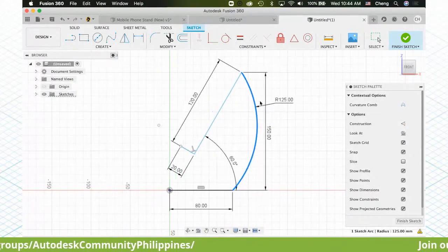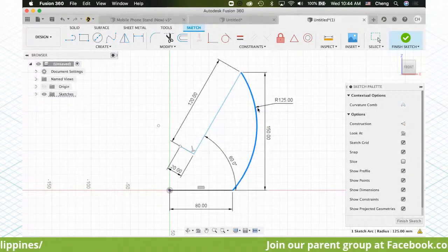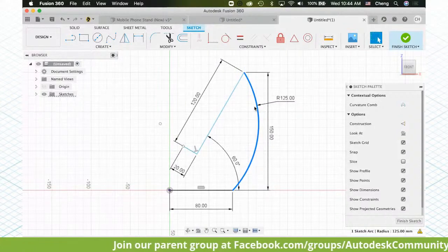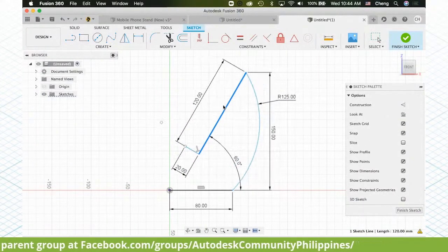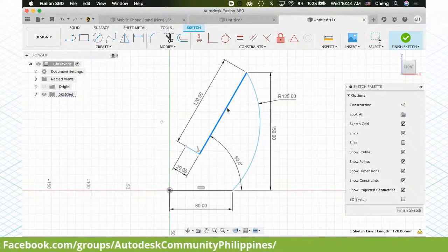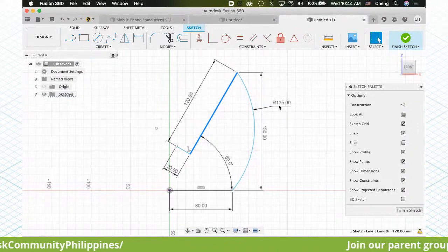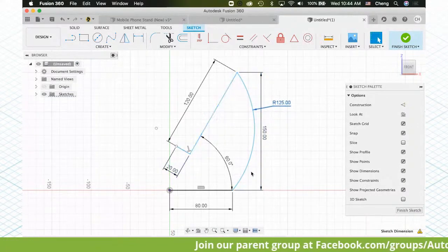So the next item, you can do a ground lock, but in this case, I don't want to lock it first because I want to look at the model outcome later on. So I temporarily just leave this model free to move. Later on, we will fix this if there's a need to. If not, I am just going to leave it as it is.